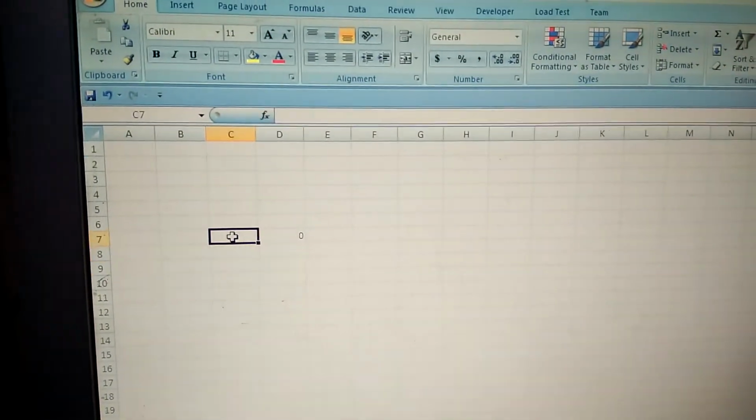Now I will plot the n values. Let me show you what this n is. I have this equation, sine of 2 pi by N into n, and this is my f of n I am trying to plot. Here 2 pi is the period, that means a 2 pi, 360-degree phase change. Within this phase change, how many samples do I want? If I say 8, it means I am going for 8 samples: 1, 2, 3, 4, 5, 6, 7 and 8. So these are the 8 samples.